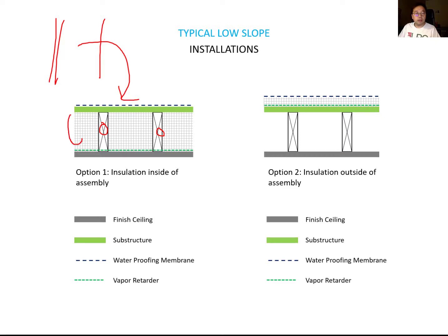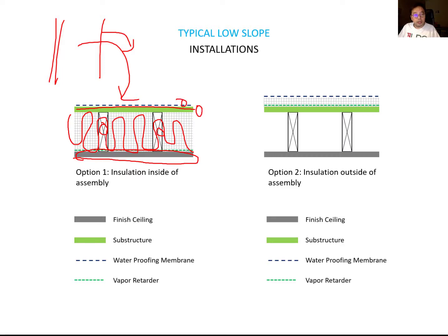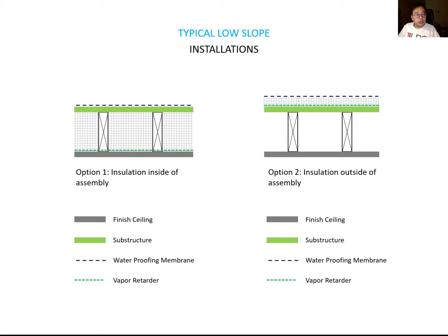And then remember that we can add insulation inside, right? And then this is a finished ceiling. In the wall assembly you can consider the inside gypsum board, and the outside, which is exposed to the exterior, you have the cover board and sheathing. But your roof design requires a substructure here, and to protect the substructure, you need the waterproofing membrane. Once again, you need the framing for the wall, for the roof, and then you need the insulation, right?